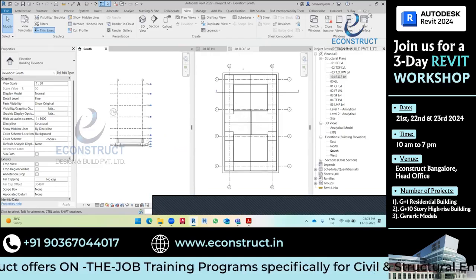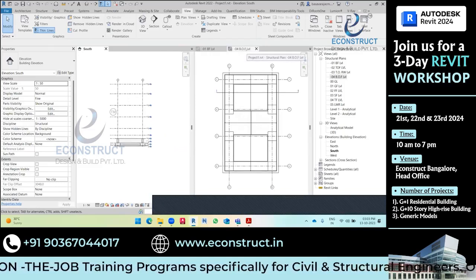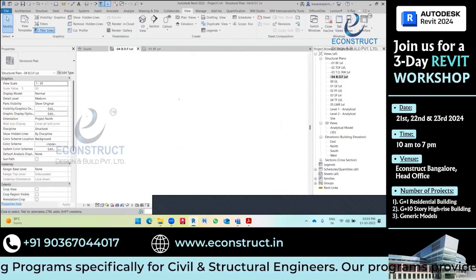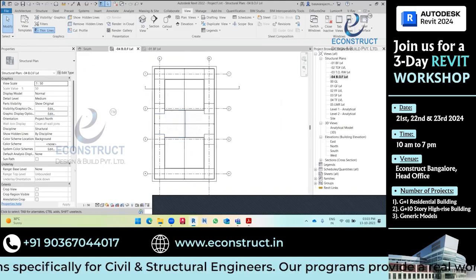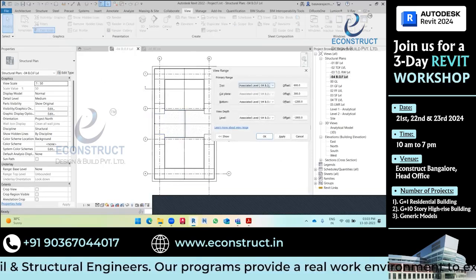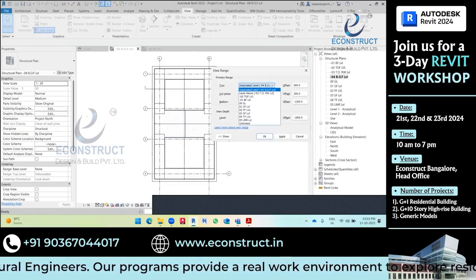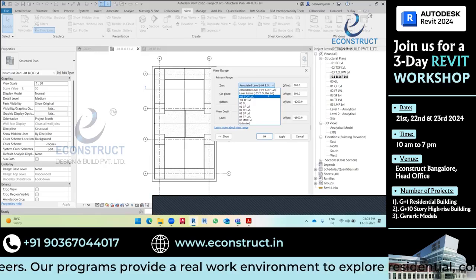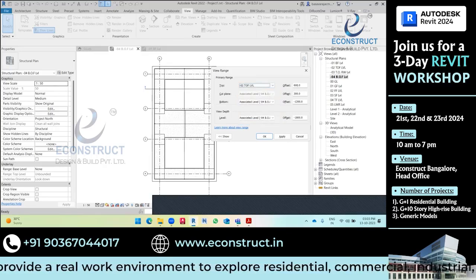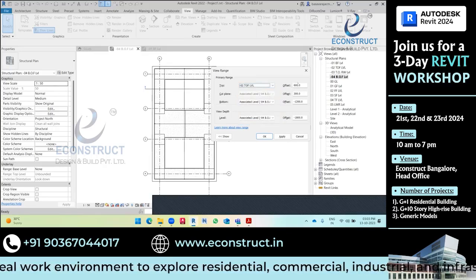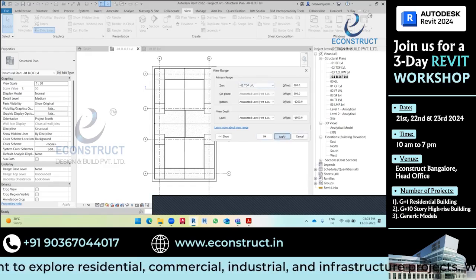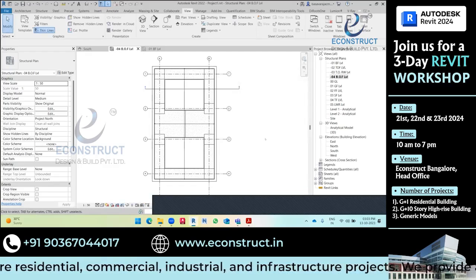Okay. What I will do, I will go to the basement of the footing now, and I will just enlarge this window. That is better. Now I will set the view range for this. For the top plane, I will take the top of the footing level as reference, and I will give a 600 offset. From the top of the footing level, it is 600 up. I will apply and click OK.